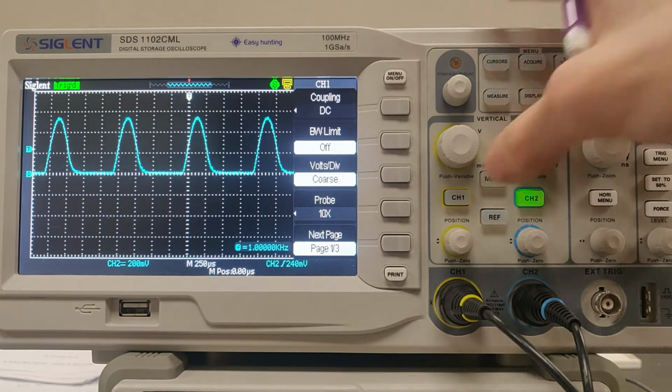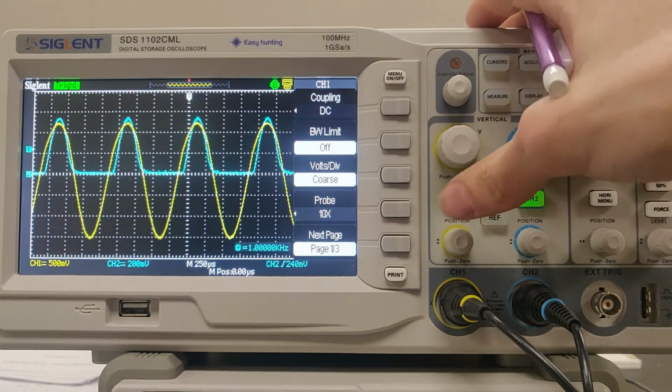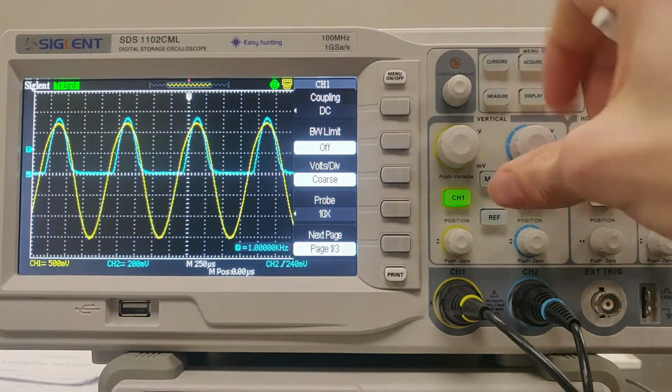In the forward bias orientation, we can see that we're still getting the upper half of our waveform, and then in the reverse bias, when the current's flowing the opposite direction of the diode, we aren't really seeing anything. We aren't seeing any voltage drop because current's not allowed to flow that way. However, charge has started to build up on the capacitor, and so even though the driving signal from our function generator is going in this reverse bias direction, the discharge from the capacitor is not. And we're starting to see how it is shifting ever so slightly to the right.